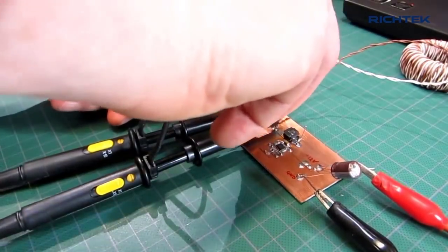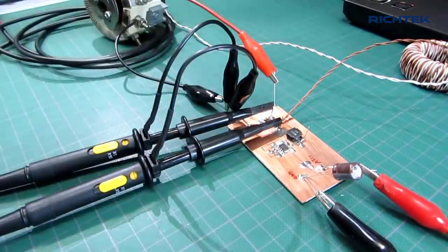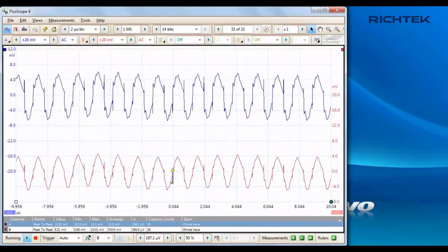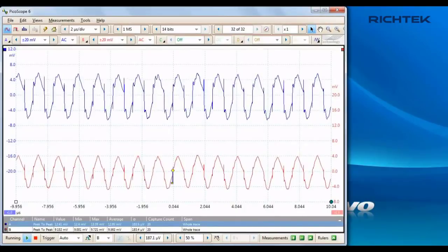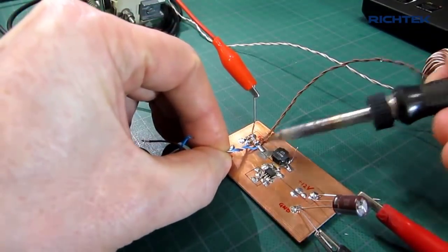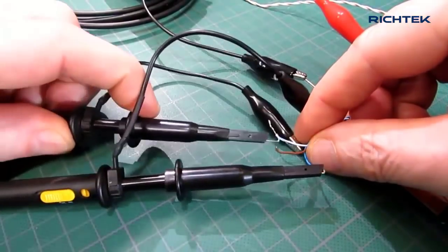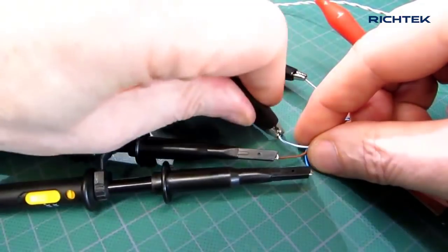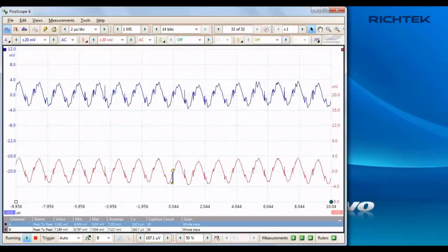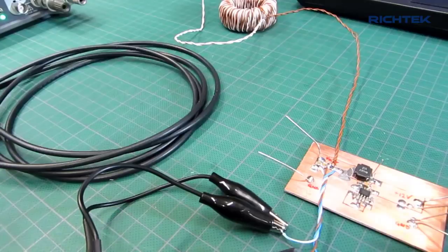Don't connect the probes with long ground wires directly to the measurement points. The inductor stray field will couple noise into the probe loops. It is better to bring the measurement point and ground away from the inductor via 3 wires twisted together and connect the probes here, which reduces noise pickup.